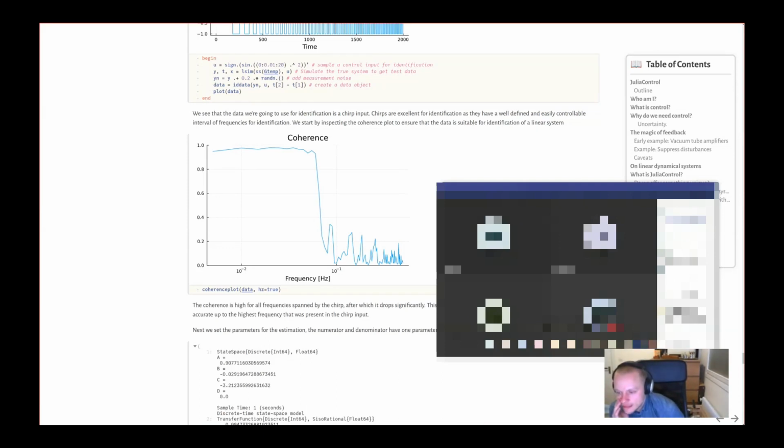Yeah, so I said I expected prediction error method, and the reason I said that is because if you implement the prediction error method, you can very easily turn off the prediction feature, and then you have simulation error minimization. So if you implement prediction error method, you get simulation error minimization for free, essentially. I have implemented a prediction error method in the package. Actually, I'm doing quite a lot of work on that just the last few days, so that will be greatly improved soon, I think. But by just turning off the predictor part, you get the simulator.